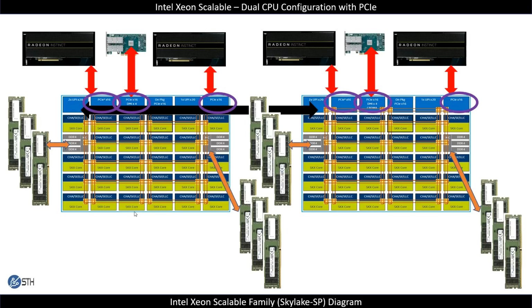Adding on the PCIe devices, we again are using the GPUs, and we have a couple of PCIe add-in cards that are network controllers. If you hear Intel discuss 48 PCIe lanes per CPU die, this is how they're getting it. They have 3 main stops on the Skylake die, and those 3 stops allow them to have 6x16 connections, which gives you 3x16 is 48.